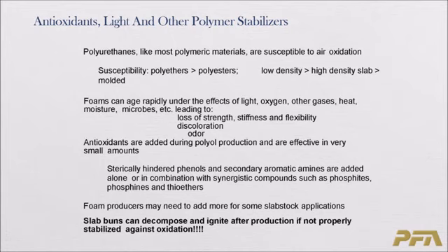I mentioned that the foam reaction is extremely exothermic, and those buns can ignite or decompose. People have set foam plants on fire as a result of that. The most common antioxidants are sterically hindered phenols and aromatic diamines.